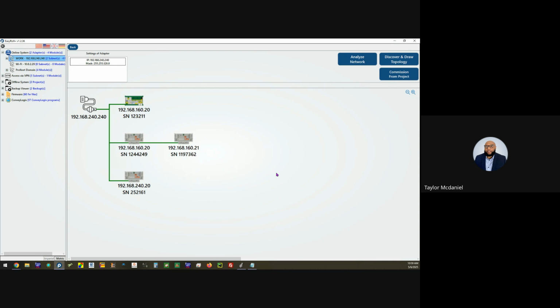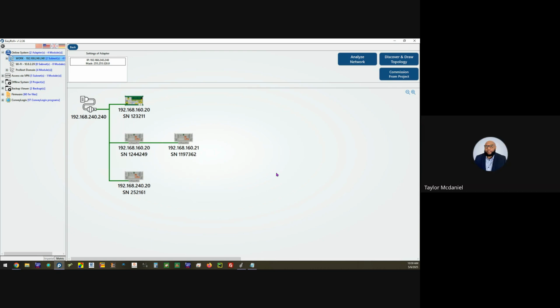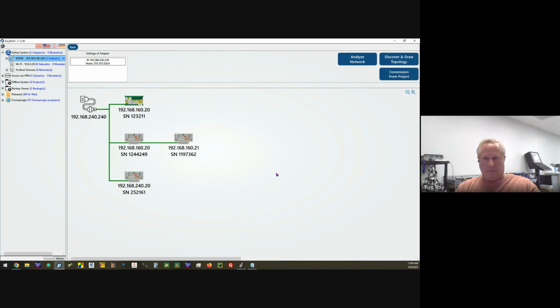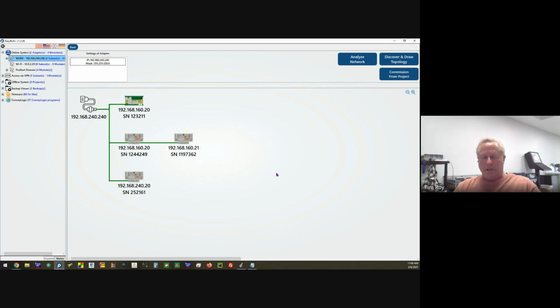Gotcha. The next thing it'll do is the IP address. It'll keep the first 3 octets, 192.168.60. Node 1, the first card, will always become .20. And for now, that cannot be changed. That's just the way it is for now. .20 is the starting point. Next, it looks at the subnet mask and it keeps it.